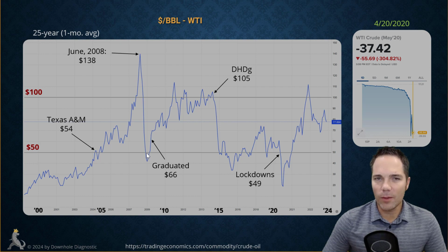And the second thing that I want to mention here is that, as I mentioned at the beginning, sometimes the price of oil is relatively high, right? If you're getting up here around $100 a barrel, that is a very good price, and you might be more aggressive. So if you have a well that's not pumped off, and you're running the well as fast as you can, you're pushing your equipment, but maybe you still have fluid above the pump. Well, if you're in this sort of condition, you might consider maybe we actually push it even harder. We expect that we're going to have more failures as a result, but the incremental increase in production is more than going to justify that because of the high price of oil.